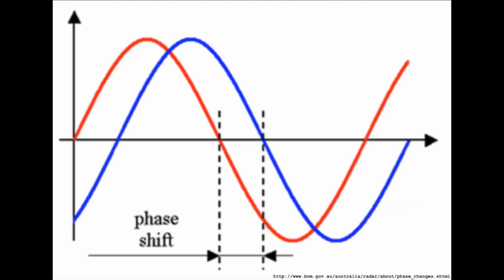A radar also has a limit on how much of a phase shift it can detect. If a target is moving so fast that it exceeds the amount of phase shift the radar can detect, its velocity will become ambiguous, meaning that the radar may think that it's stationary or moving the opposite direction at a much different velocity than what it actually is. The maximum unambiguous velocity dictates the maximum range of velocities that can be observed without this ambiguity. We're going to talk more about this later on in this module, but for now, know that as the PRF increases, so does the maximum unambiguous velocity.